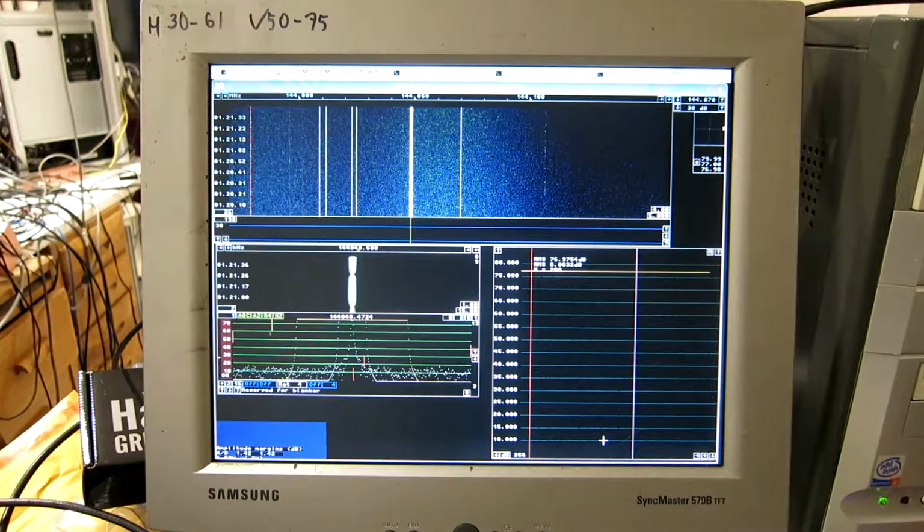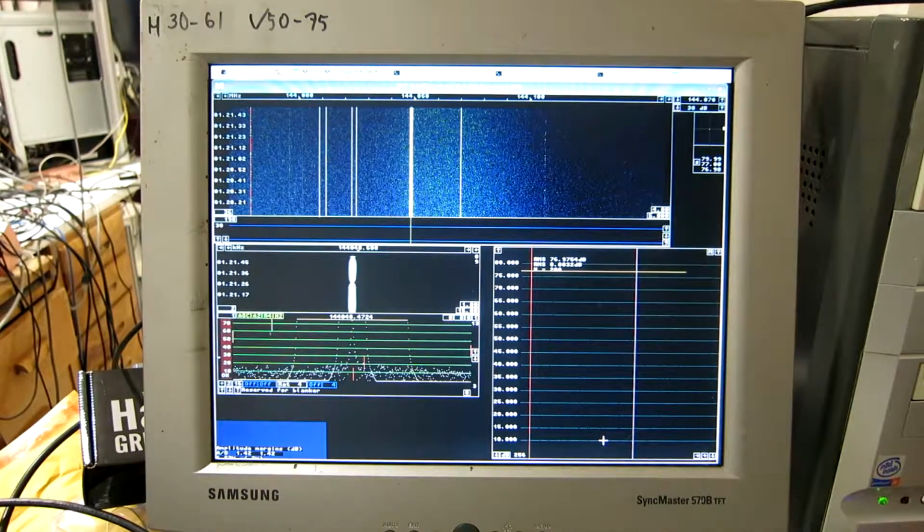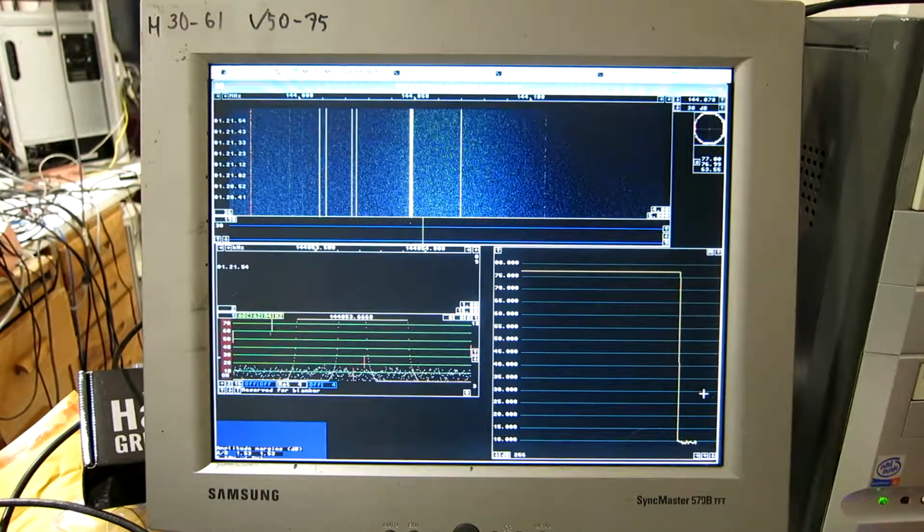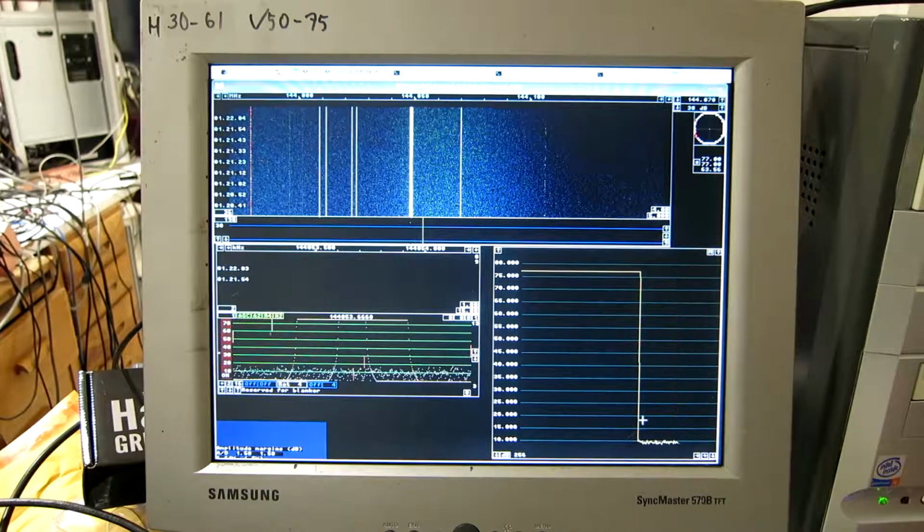I've now set the good crystal oscillator to 1.4 dB below saturation, and the level is 77 dB, as you can see. And the noise floor is here, and I have to wait just a little to see what it becomes, but it's about 10 dB. Now I think I can get a number.